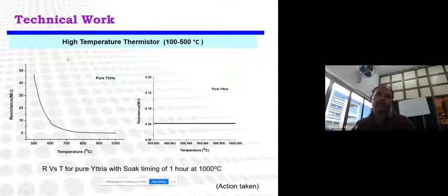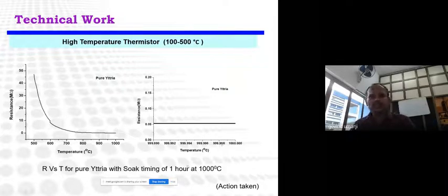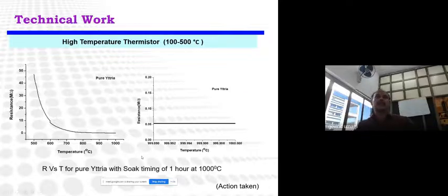Again, one of the industrial aspects is that the sensor needs to be stable for a long duration. So we followed one of the industrial standards, where we soak the sensor for 1 hour and see whether the resistance changes or varies. At 1000 degrees Celsius continuous soak, we have not observed much change, only a plus minus 0.01 degree variation. That is much better in terms of reliability.